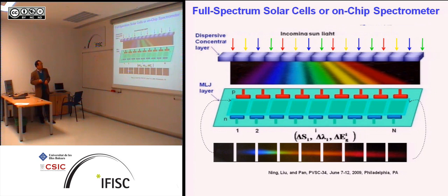Now, this is the further device specification of this sample, such as how many subcells. I can do the lateral PN contacts laterally. The sample is just a grating, for example. Initially I thought I just need a grating. When the solar white light comes in, the grating splits the colors into different wavelength bands. So what I do is optimize the division of the subcells so that the right wavelength window goes into the right band gap intervals. That's all I need.